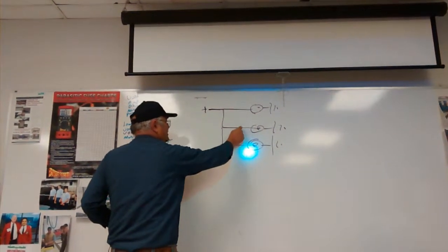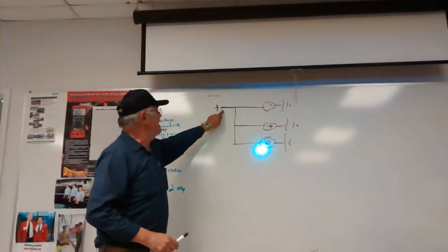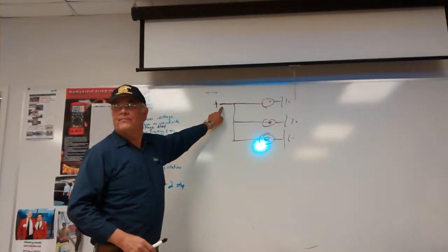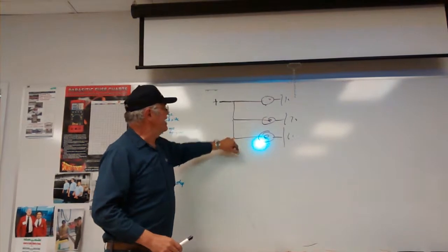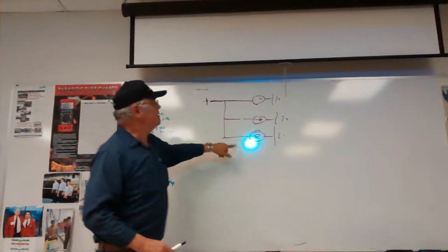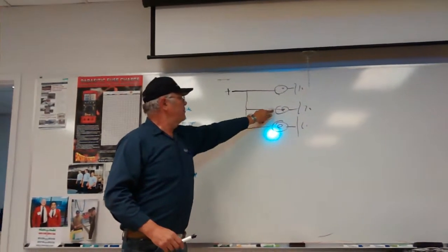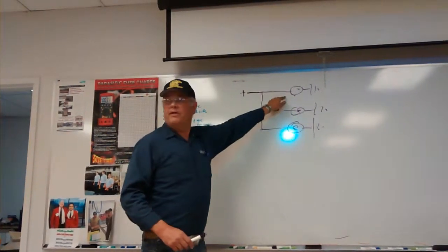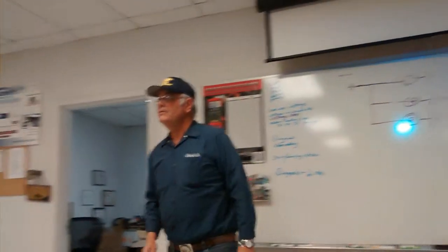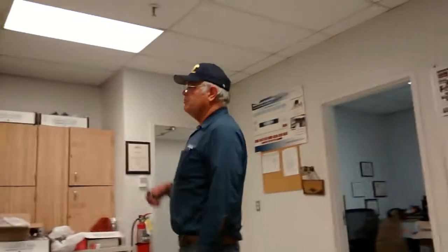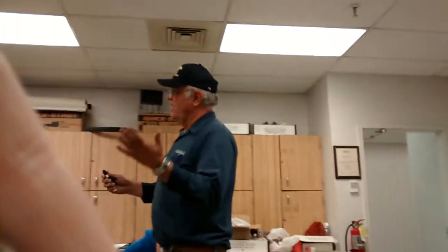Okay? These are side by side. They're all fed by the same voltage. And in this circuit, since they're side by side, if this one burns or breaks off or has an open, both of these others will continue to work, correct? Yes. Okay. That's what we want on the cab of our truck. I don't have time to go through voltage drops and everything in the circuit. This is just a reminder.